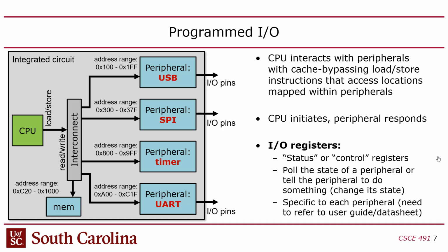There's a flash memory that's internal, right? That's where you store your program. That's a non-volatile memory. But then it also has RAM, like any other processor. That's a volatile RAM. And the RAM and the flash will have their own ranges. But all of these ranges come from a single global address space, right? You have one address space, and that address space is divided into sections for all the peripherals and all the memories, right?